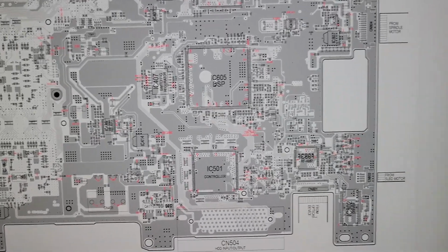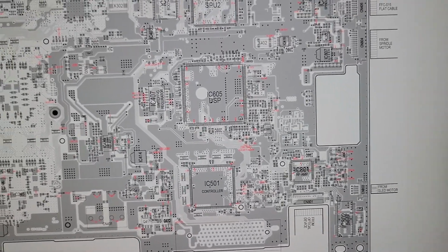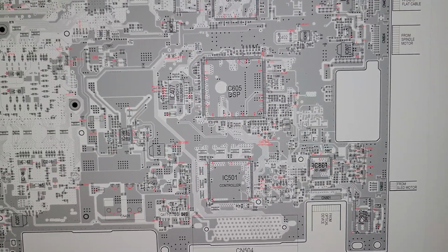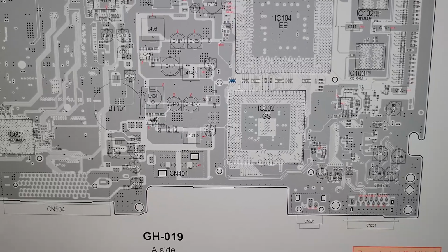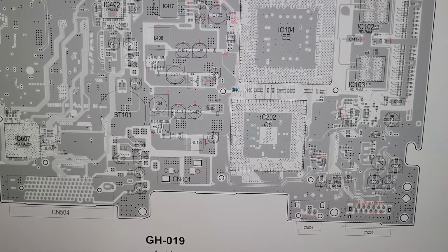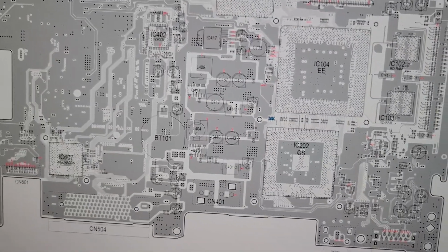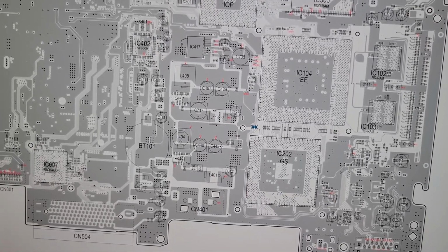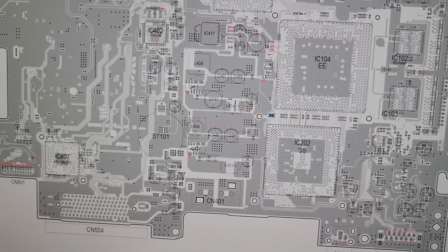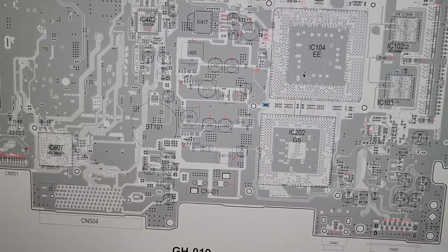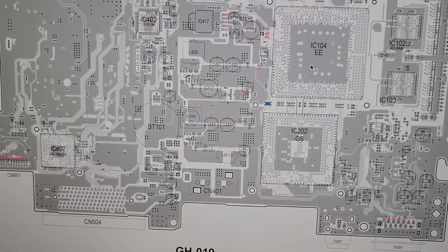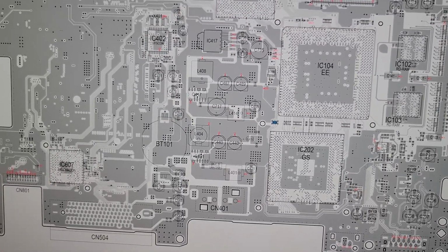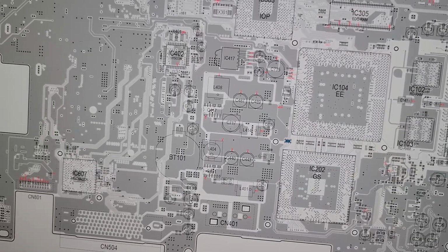There's the RF amp. Like I said, this is just a learning video to show you guys that that's how I fixed that one, was RB109. You're going to need a donor board for it. I don't recommend you jumping it, because these two chips look for certain resistance. If it doesn't have that certain resistance, it won't boot, and you won't have any video.